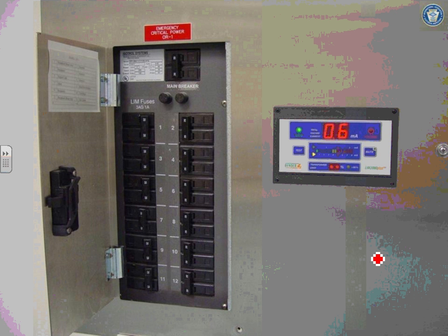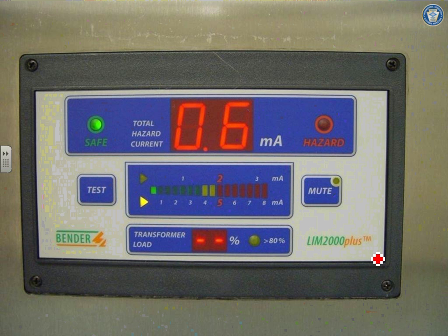If you ungroup the system, the code requires you to monitor the current to the ground and trip. So you have to have a monitoring system to be able to decide if you have a ground fault. This is typically in the hospital. You monitor your milliamps, and you can alarm or trip on a ground fault. So if you are to use an ungrounded system, you must have a way of monitoring that you have a ground fault.